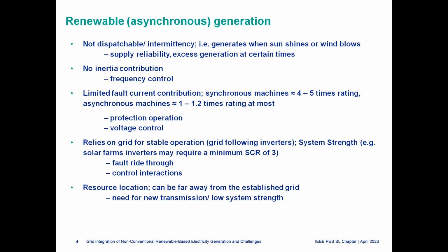And another main issue is that most of the present day inverters, we call them grid following inverters. That means they rely on the power system, or the existing system voltage waveforms, for their correct operation. They follow the grid voltage. We call them grid following inverters. So if the system strength is low in a particular area, sometimes these grid following inverters will struggle to maintain stable operation if there is a disturbance. And there can be control issues as well.